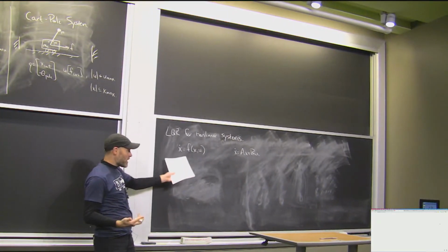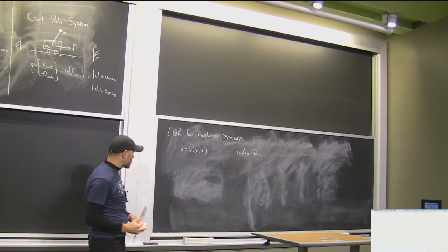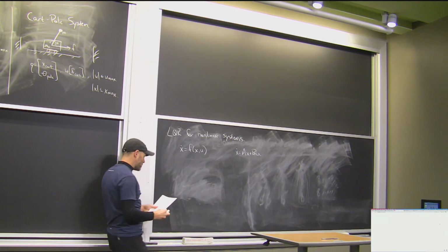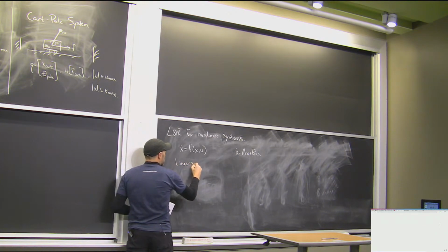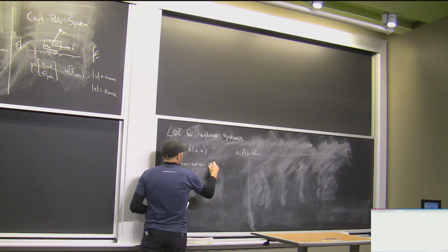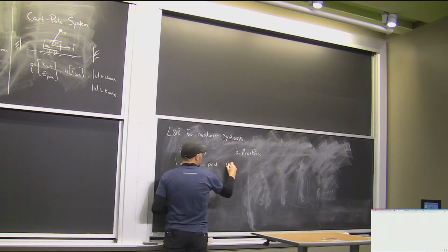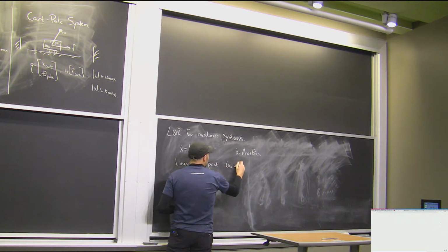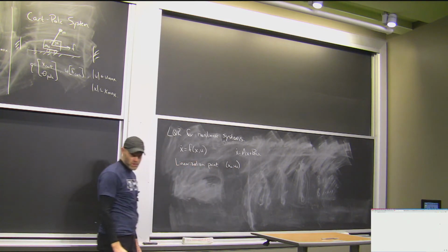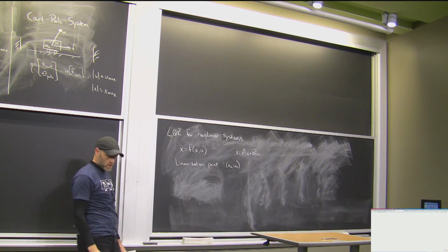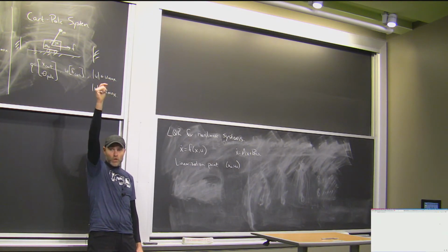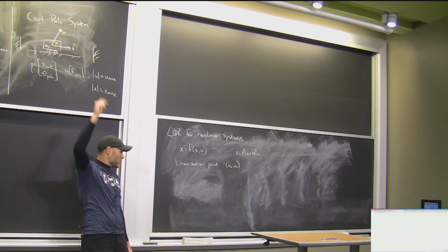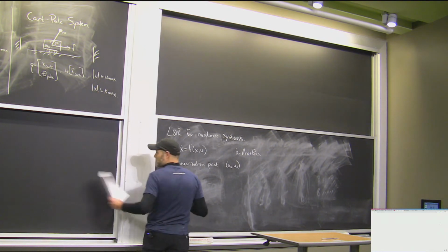I mean, you can linearize a nonlinear equation. What does that look like in the dynamical systems sense here? You're going to pick some linearization point. That means a nominal state and control pair. For us, we're going to pick the state when we're at the top and the u that is 0, because that would be the equilibrium and the zero cost configuration.